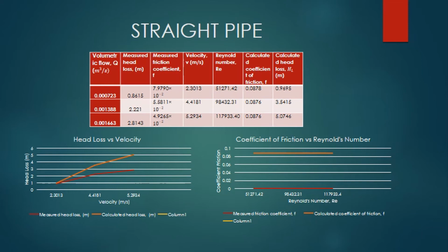However, from the data of measured and calculated values for the head loss, the measured values are lower than calculated values, which is abnormal since some values are distorted by some errors, including due to the lack of maintenance and calibration on the apparatus. Thus, the increasing of the velocity will decrease the value of the coefficient as well as increase the value of the head loss.